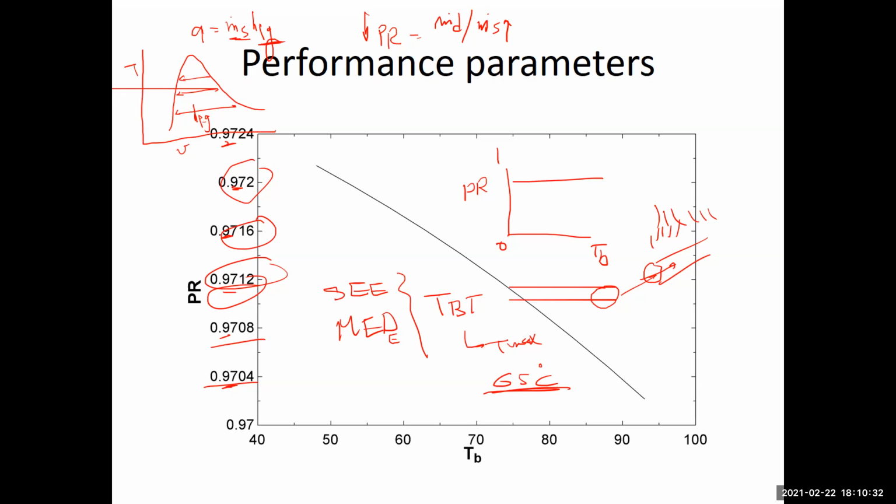Then some people have started working on pre-treatment of the seawater, coming up with novel ideas, like using nanofiltration, or some of our work that we have done before, where we have a filed patent that talks about ultrafiltration with a reduced graphene oxide coating of the membrane, so that we prevent the multivalent ions from passing. We are just allowing the sodium and the chloride to pass, and we are not allowing the magnesium components, the carbonates and the sulfates, because these are the ones that are responsible for the hard scaling and soft scaling.